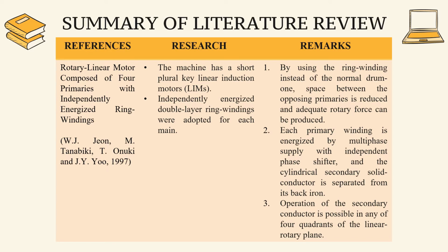Each primary winding is energized by multi-phase supply with independent phase shifter, and the cylindrical secondary solid conductor is separated from its back iron. Operation of the secondary conductor is possible in any of the 4 quadrants of the linear rotary plane.